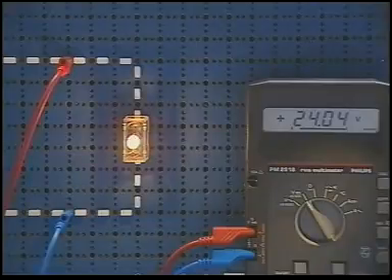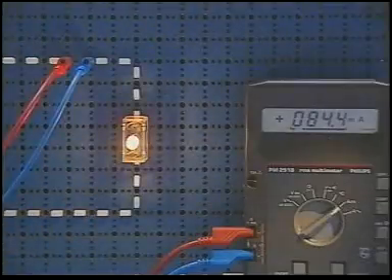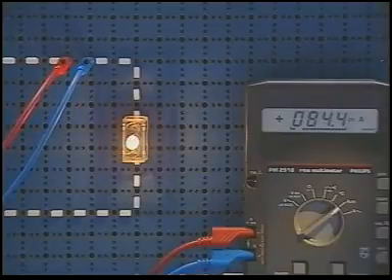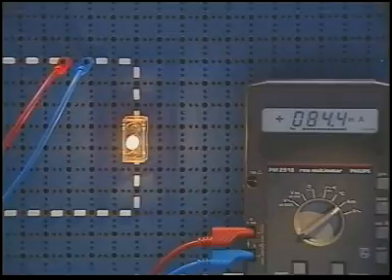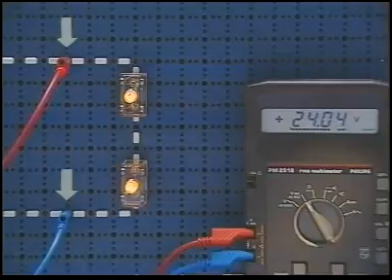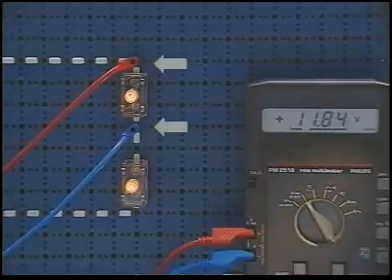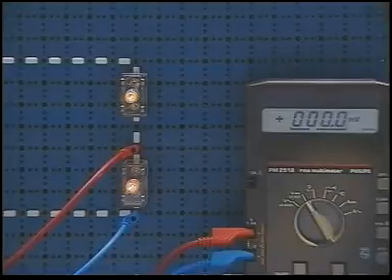An experiment to demonstrate. The white lines indicate electrical lines. The voltage V is 24 volts. The lamp has a constant resistance of R, and as we see, a current of 84 milliamperes flows. If we double the resistance by adding a second lamp, the voltage at the source is still 24 volts. But the two loads connected in series have divided the voltage according to their resistance. So we have 2 times 12 volts.